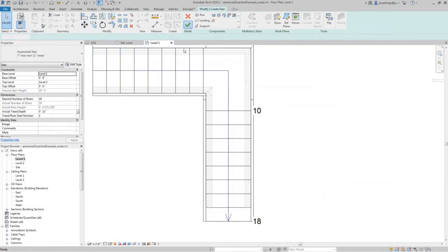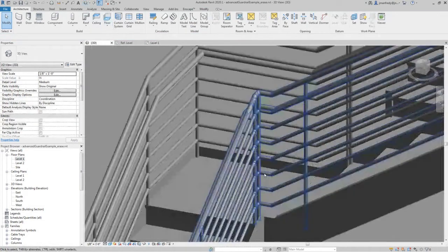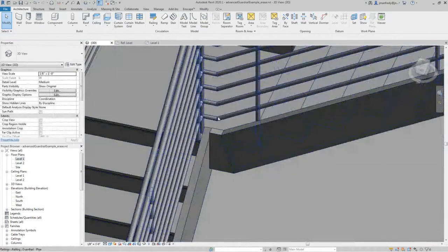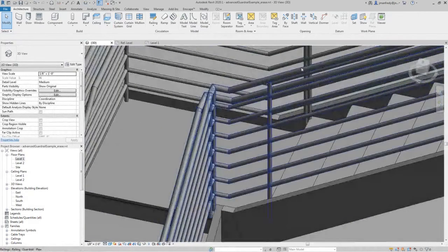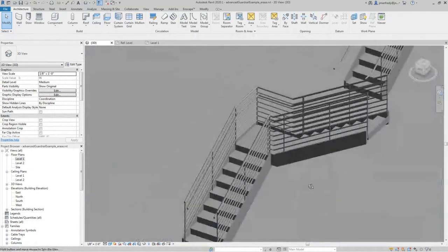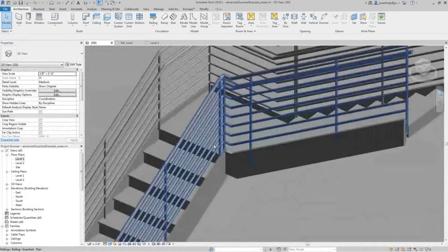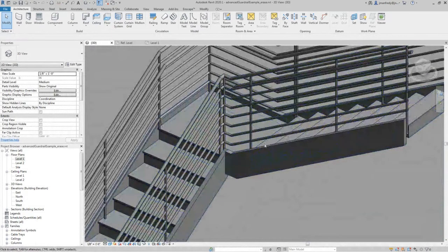If I hit OK and take a look at that stair, you see what happens here? Moving it back, that's more than a foot, made this top rail come down, flatten out long enough to make the turn, and then meet this member coming up from below and do its job. And so that remedies some weird conditions that happen when this riser and that riser there are too close together.